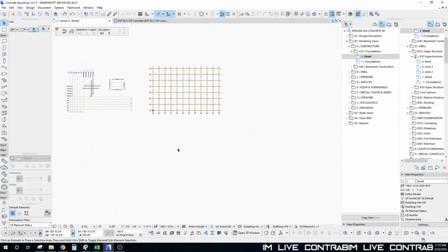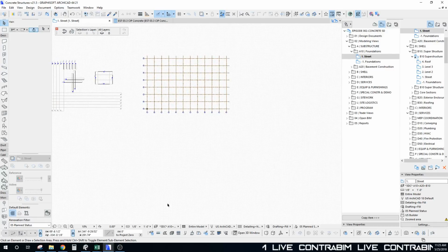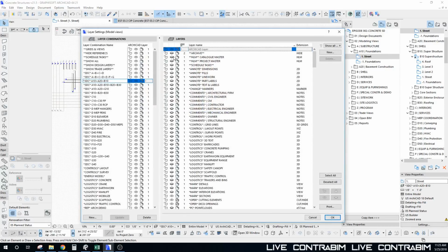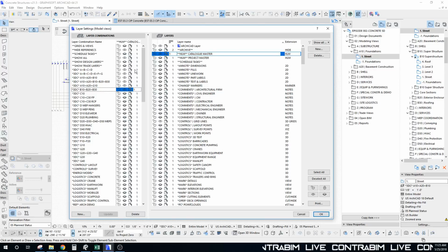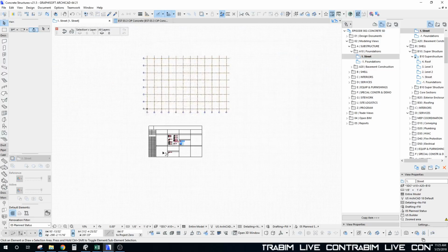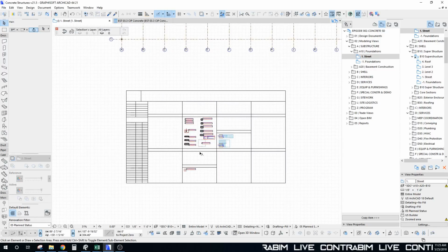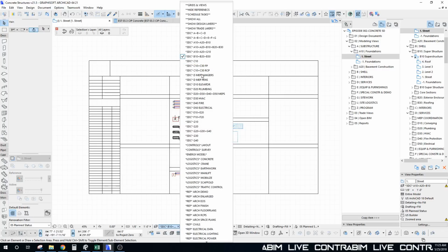And I can see now my modules disappeared on me, and I got a feeling that that's because my hotlink module is not turned on in all my layer combinations for these combinations of systems. You can see there I got A10, A20, B10, and a bunch of different combinations based on these systems classifications. And if we turn that back on, we can see those elements have populated.